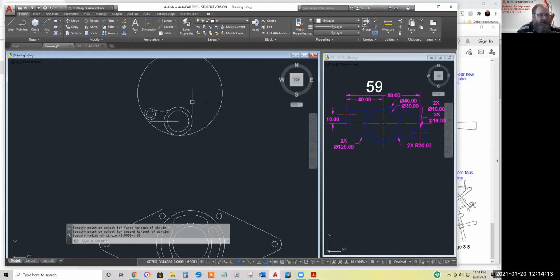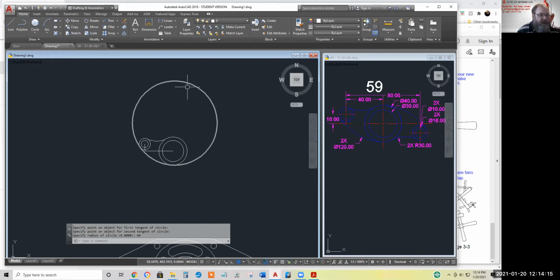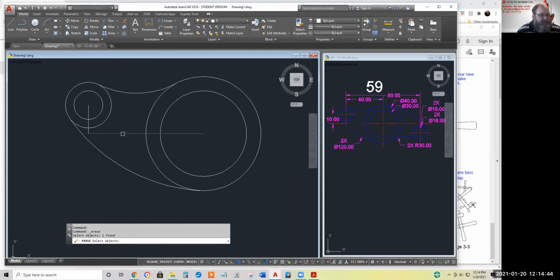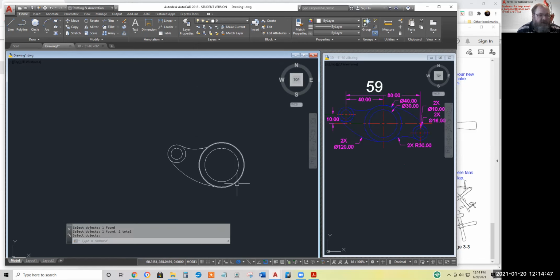Now we've got to trim away the garbage. For good measure, it's a good idea to have everything visible that you're going to trim. In newer AutoCADs, I think 2019 or 20, it's not so important, but still a good habit. Click trim, select all easily for the cutting edges, and click there, and away it goes. Let's erase our guidelines. Hit enter.